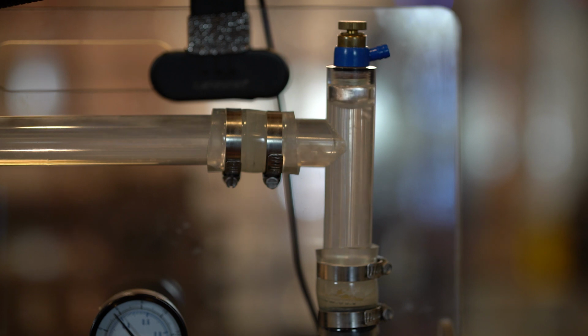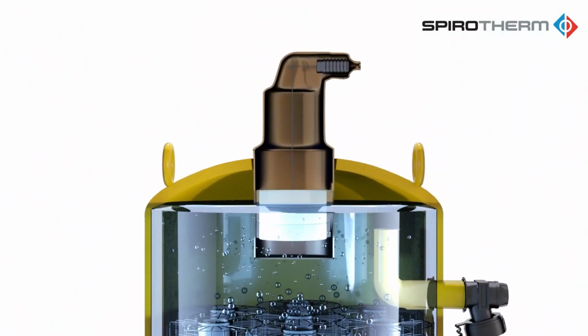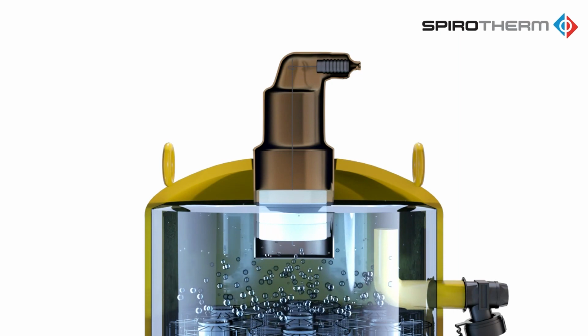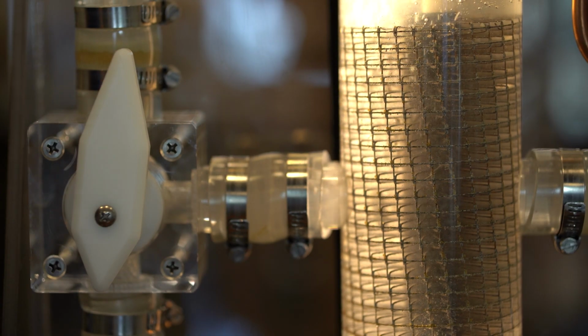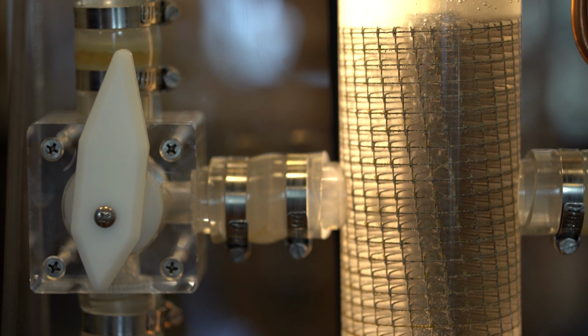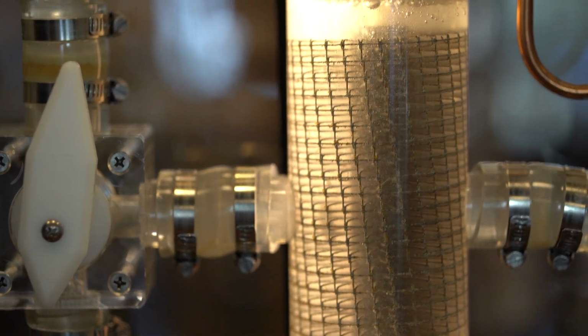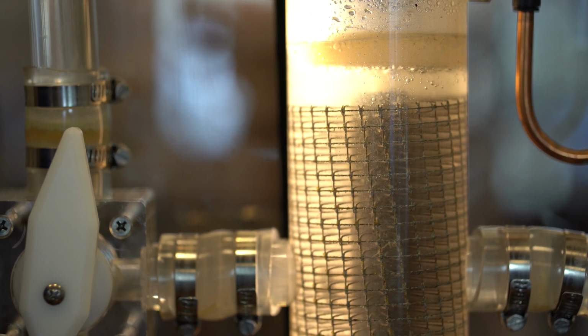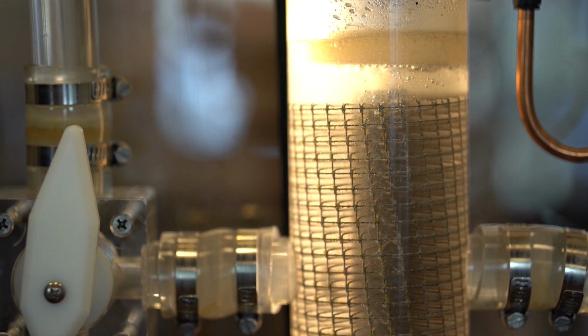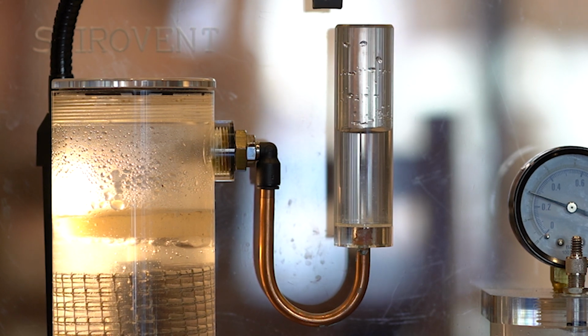I used to live in Michigan when I was growing up, and we had in-floor heating. My room was in the basement, and you could hear whenever the zone above me would call, because we had a drop ceiling. You could hear the water going back and forth and back and forth. When I was a kid, I thought, oh, that's really cool, the heat is on, because you live in Michigan, the heat needs to be on. But you could hear the water. You shouldn't be able to hear water moving through the system. So when you hear water, that means there's air in it.